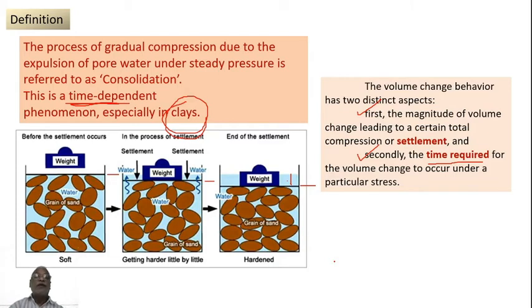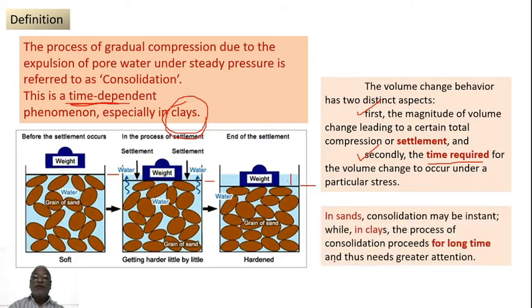Okay. Now in sands, consolidation may be instant. As I told you, because the permeability is quite large, instantly the water under pressure goes out without any difficulty.